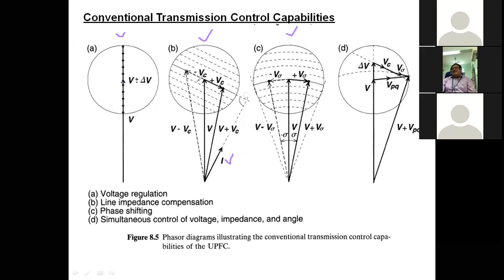Shunt capacitance sometimes has a charging current that exceeds the voltage drop in the series inductor, so you may have the Ferranti effect, that is receiving end voltage greater than sending end voltage. That is only under special conditions, a lightly loaded long transmission line.